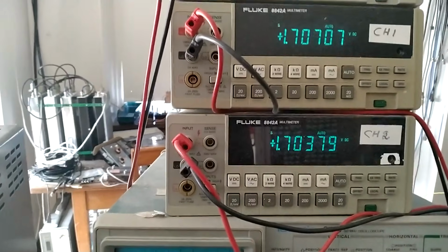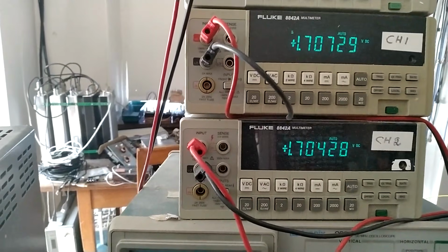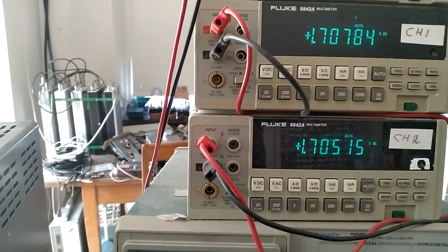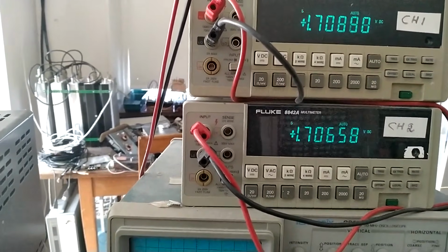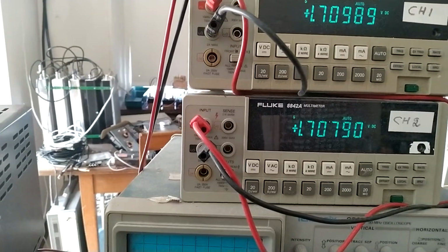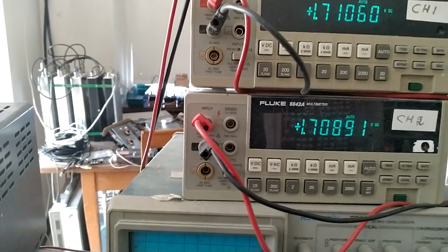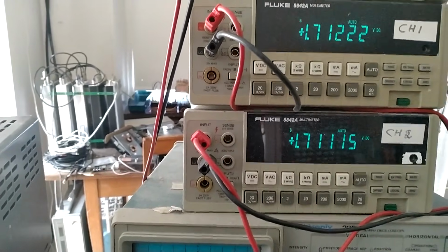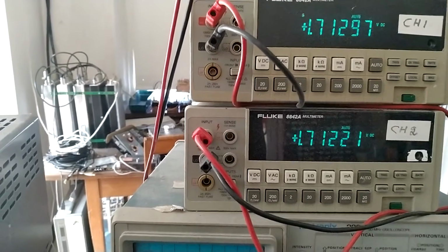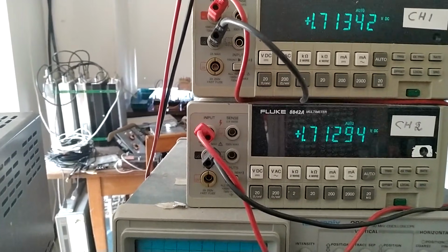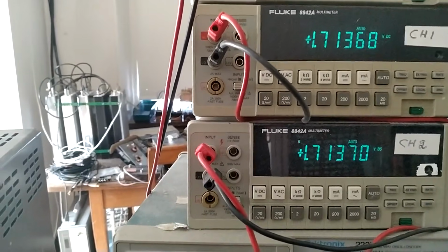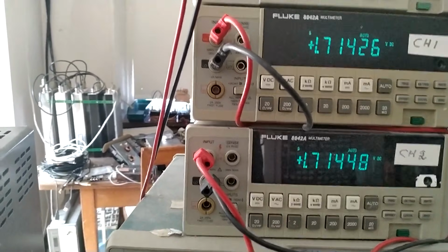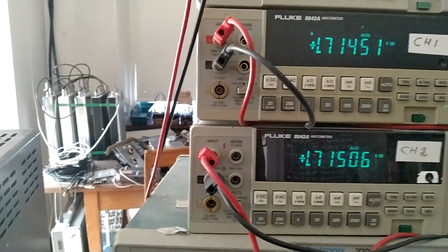And these are the voltages of the PLL for both. The range is from 0 up to 5 volts. So 1.7 is a reasonable level. And it goes up and down, as you can see. And that is in order to keep track with the noise that is in the oscillators.